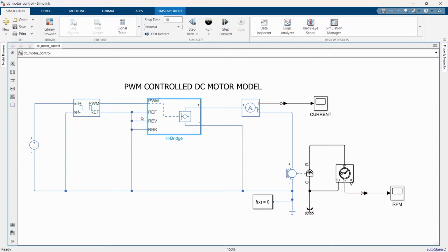Next one, the reference port. It provides a common reference point for our voltage measurements within that block. By short circuiting this port, we can establish the common ground for voltage calculation. So that is why we did that. Do you have any doubt in this?